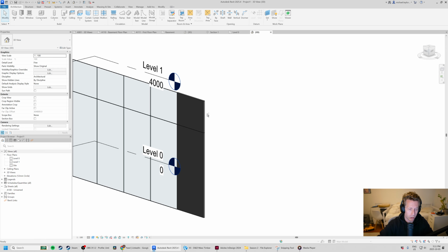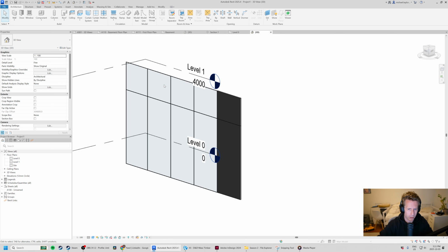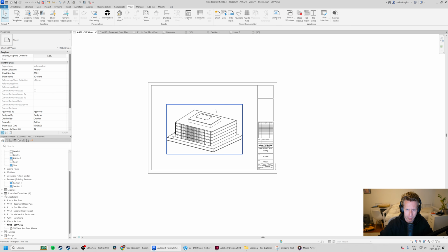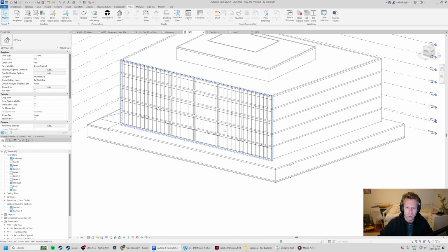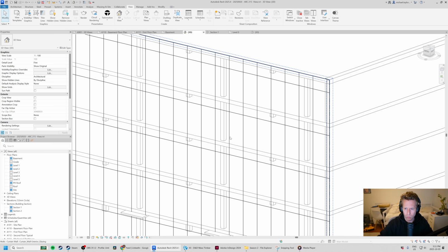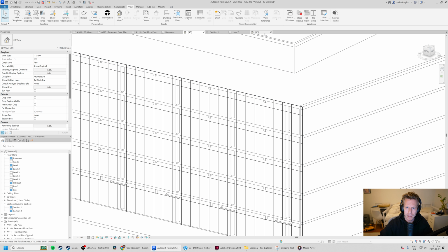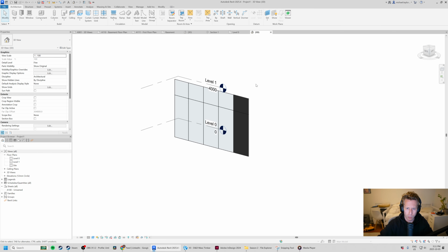These are really going to be what are called your spandrel panels. Spandrel panels will be over things like slabs. Maybe you've got some spandrel panels you're trying to cover something. For instance, in our office building, we probably use these over the CLT, and where we've got the limit of where our raised access floor is living. Just some ideas about where we might have spandrel panels.